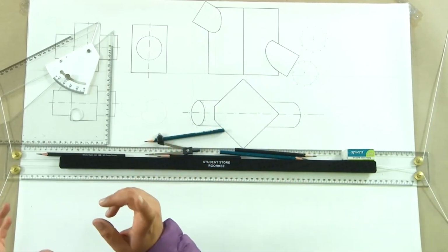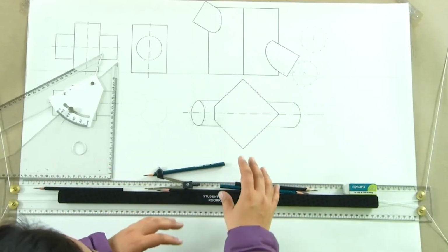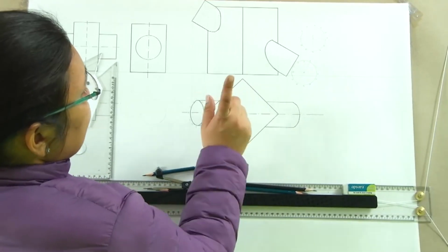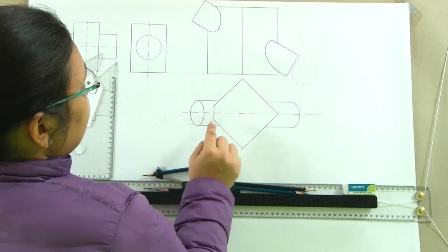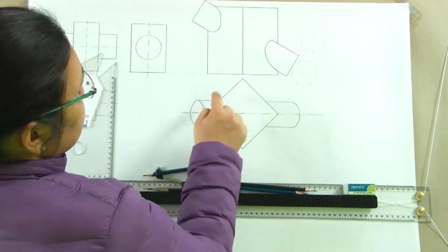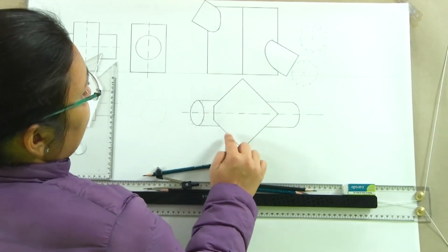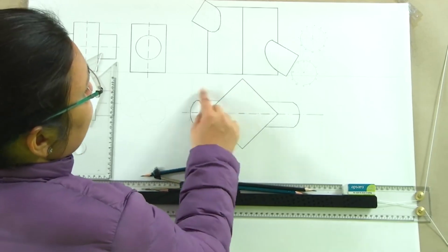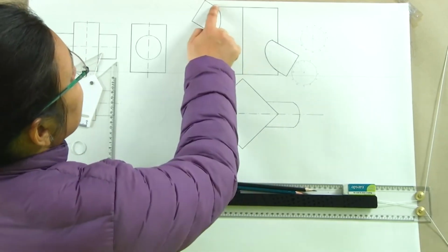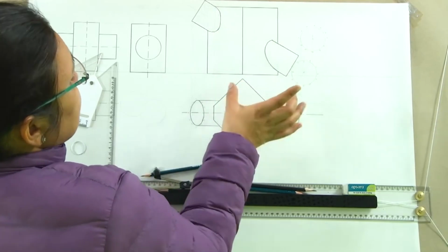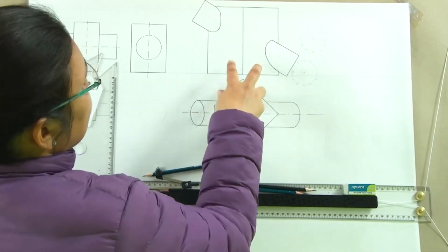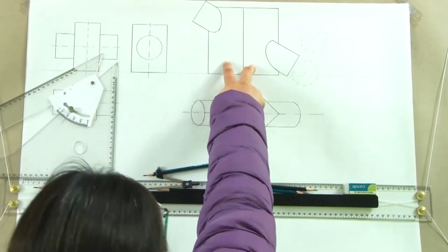If it was a circular solid, so instead of a square prism, if we had a cylinder, in that case instead of these 4 edges which are here, we would have again these 12 points, and wherever the generators of both will intersect would have determined how these cylinders are going to intersect. That is how we would have done in case this was a cylinder.